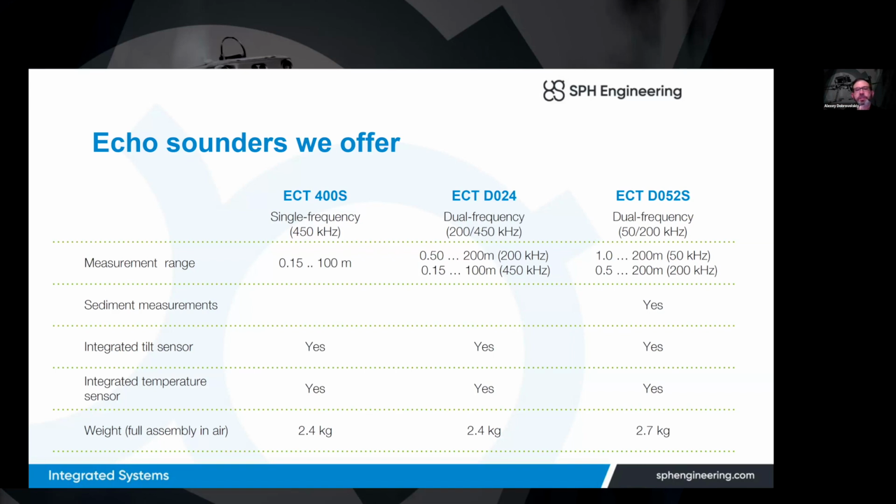For what it can be useful, you can better estimate water speed, sound speed in the water, because it depends on the water temperature. So by default, our software and Hydromagic will use 1500 meters per second as a sound speed, but if you know the temperature of water, you can make corrections for the sound speed.